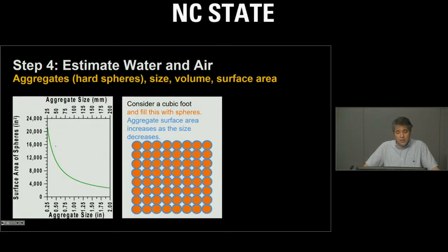So again, we talked about this. We said that we want to use aggregates that are larger. The reason is that the larger aggregate we have, the less surface area we have. For example, if we want to consider a cubic foot and we want to fill it with spheres, they are all spheres and they are the same identical size,